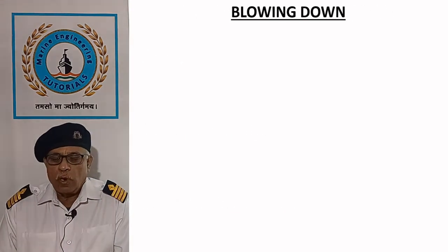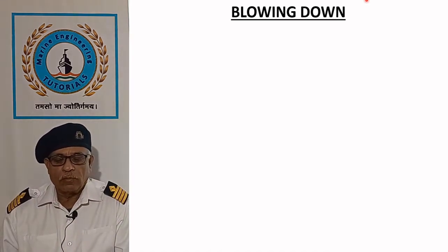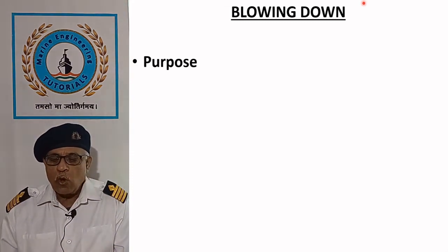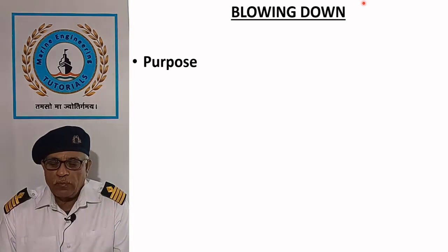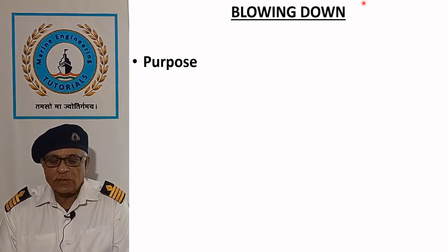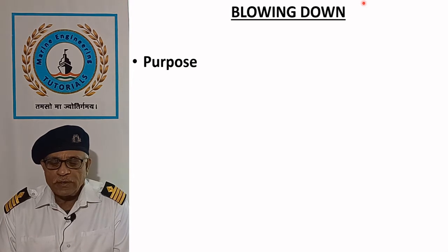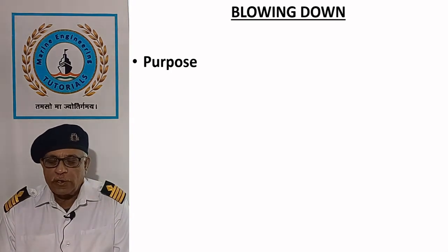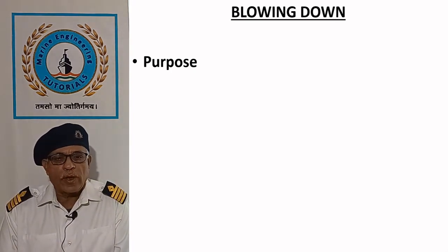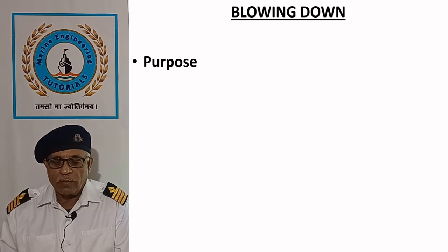Blowing down. Blowing down refers to draining the water from the boiler. Purpose. Blow down may be carried out to remove the contaminants such as oil, precipitates, or dissolved salts. Blow down is also carried out to facilitate internal inspection or repair of the boiler drum.